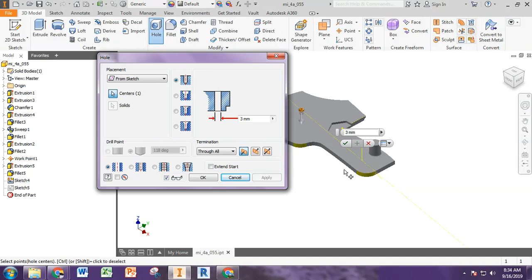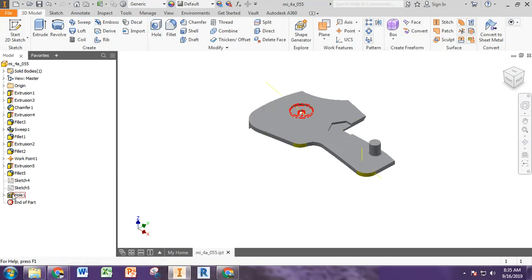and it wants you to click the Counterbore option. So these are the different hole styles that we talked about. If you hover over them, you'll see there's just plain drilled, Counterbore, spot face, and countersink. So to do Counterbore, we're going to click there. It wants the main diameter to be 20, or the counterbore diameter, and the depth to be 2. Then the hole diameter through to be 6, which is a pretty wide and shallow hole, but we'll go with that. So now you have your first hole here on the feature browser.